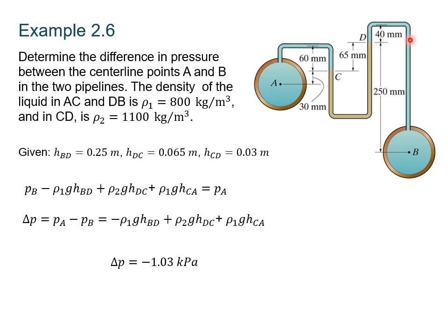So that'll be the same pressure here as it is at D because we're moving horizontally in the same fluid. So what's the pressure here? We're moving upwards, so the pressure is going to go down. So it's going to be minus rho 1 times g times the height difference from B to here, which we know is 0.250.